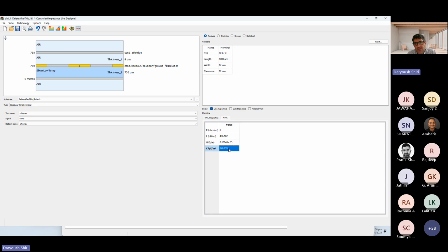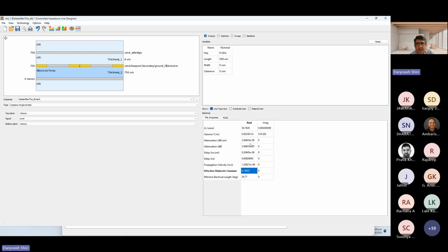That helps you calculate the total capacitance of the resonator, and also the capacitance of the transmon. If you have a cross-shaped transmon, approximately you can say that I have 4 arms of the transmon, and each one has this much picofarad per meter. So approximately I can have a ballpark number for the capacitance of my cross-shaped transmons, and this is the inductance per unit length.